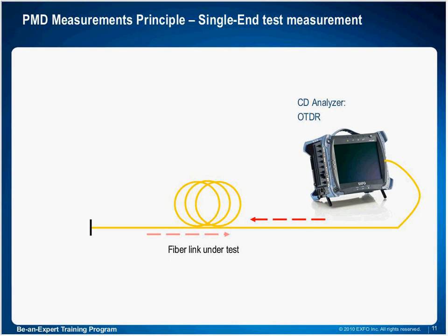There's also the fact that receivers have an internal clock, which means that at every unit of measurement it is expecting to see a 0 or a 1. When dispersion occurs, the times at which these data bits arrive will be shifted. They will no longer fit into the appropriate time slots in that clock.